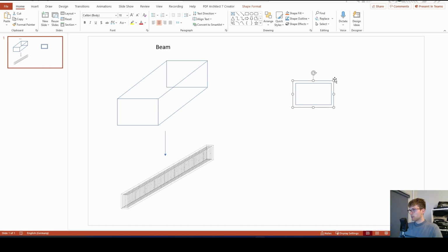So that means all the lines from the cross section, and from there we are basically offsetting those lines inside of the element. And then we basically get our rectangular, that's the center line of our rebars. And from there, we are gonna just get those corner points.